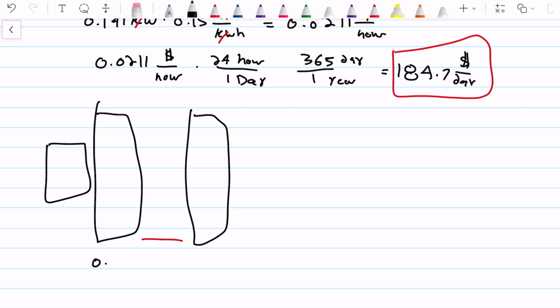And then these were, let's see, what were these? These were 0.25 centimeters, 0.0025 meters. Same thing. It's important to keep everything in SI units. And then what will be the savings in energy of this window? And then assume that the heat transferred across the space is only by conduction.